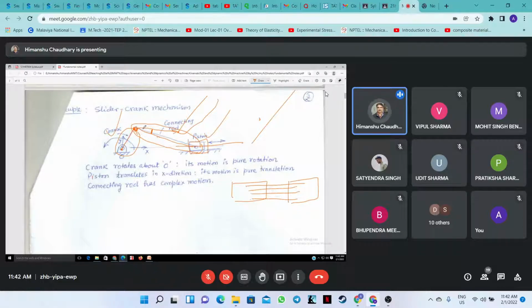So the motion of this link line is theta. This is alpha. So by knowing theta and alpha, and knowing the position of this point, and this is the length L, which is again fixed and will not change. So knowing the length L, the angle theta, the angle alpha, and the position of this point, I can find the position of any point P. So that way I require x, y, and theta.